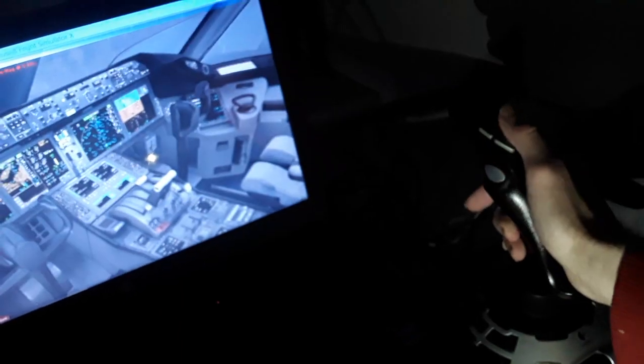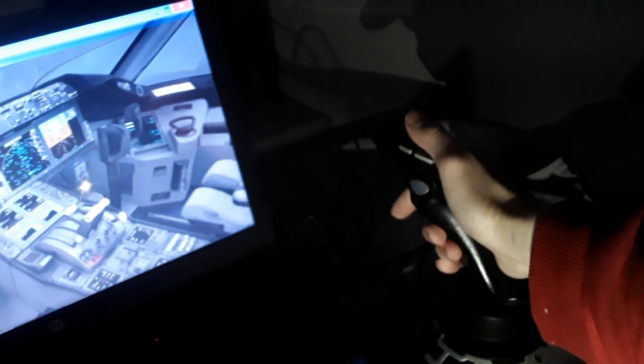You have also in the Boeing similar things. Also climb and descent in the Airbuses: 30 degrees climb and 1.5 Gs climb, and minus 15 degrees or minus half Gs of descent. The G is the acceleration of gravity. Also you have other protections, the alpha floor protection and speed protection. So you have in the Airbus, the Boeing similar things.